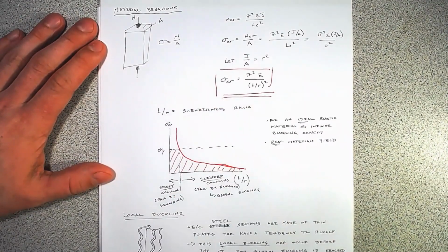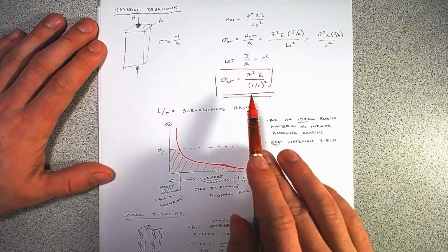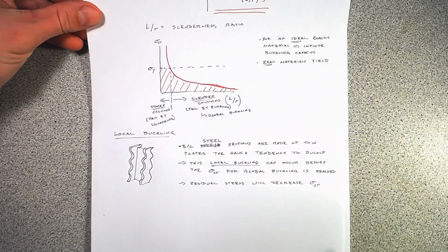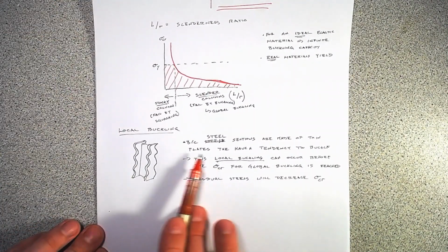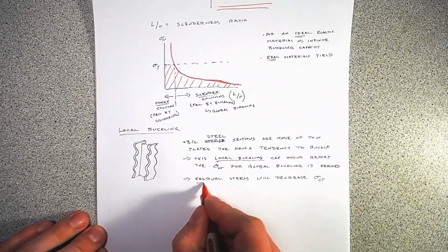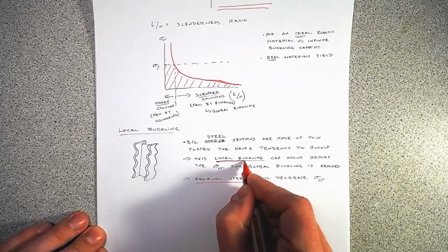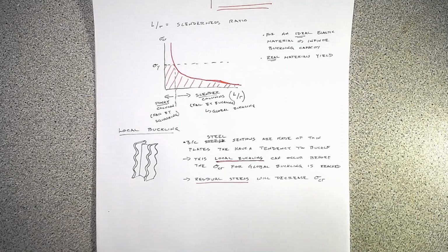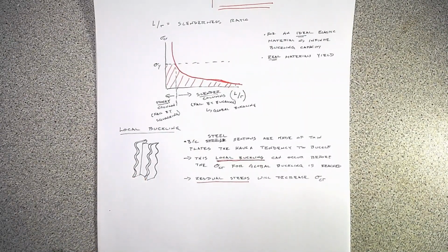And because it's buckling, we still bring in our slenderness as our controlling factor. And then it's these two things, either local buckling or residual stresses, which will further reduce what our section capacity is. We'll step through all of those in these coming videos, starting first with the section capacity where we look at this local buckling effect, and then look at global buckling.